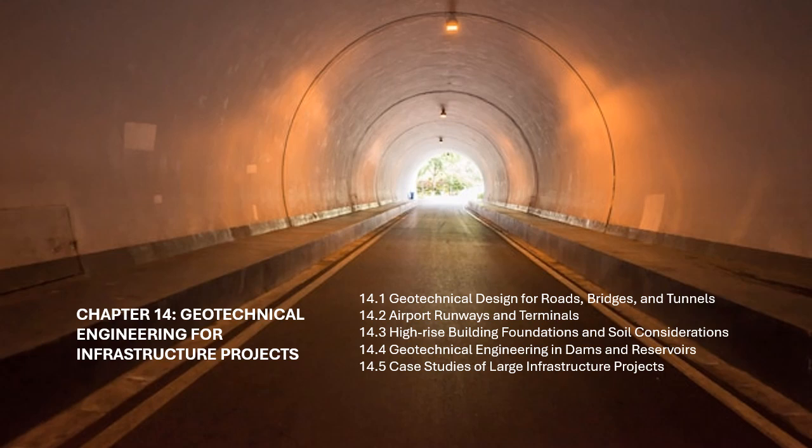Seepage monitoring. Ongoing monitoring of seepage is critical for detecting potential issues before they become serious. Engineers use instruments such as piezometers and seepage meters to measure pore water pressure and flow rates in the foundation. This data is used to assess the effectiveness of seepage control systems and to ensure the long-term safety of the dam.